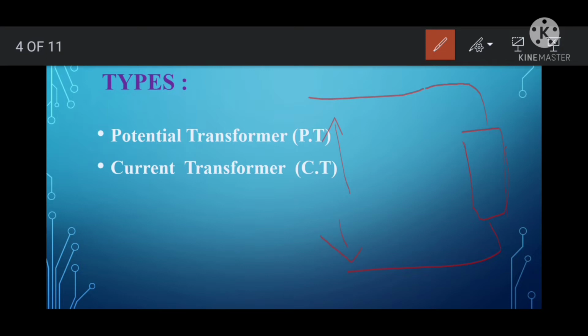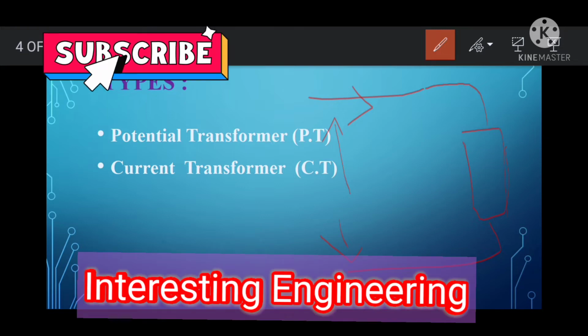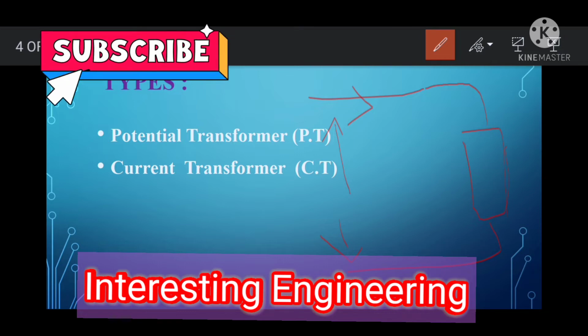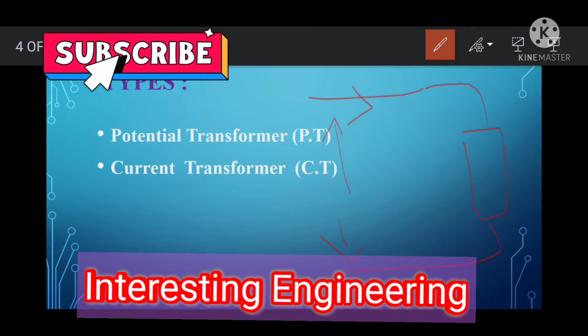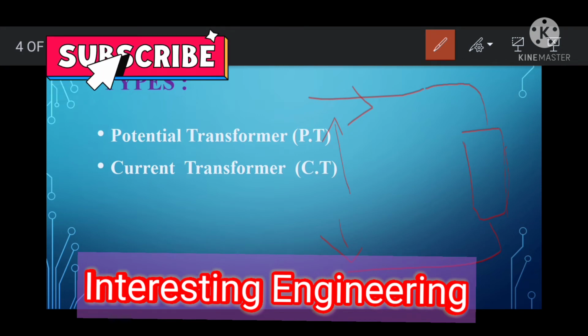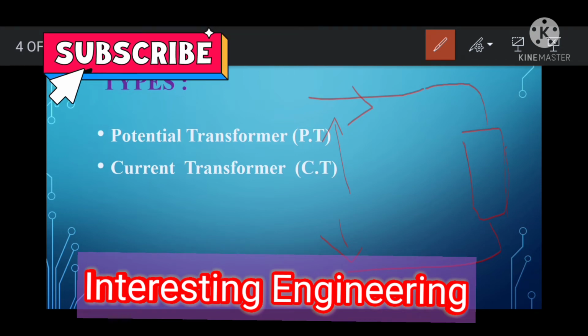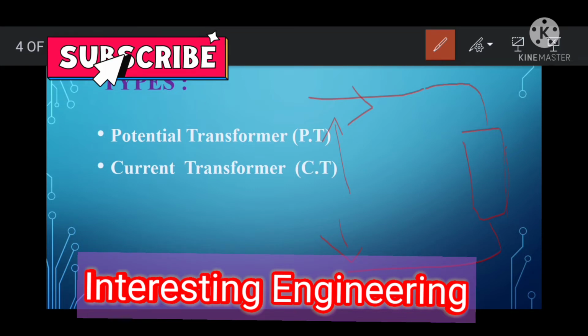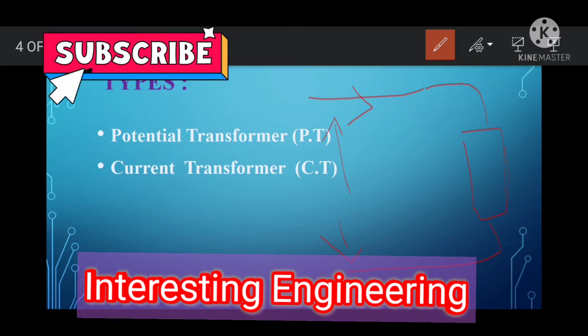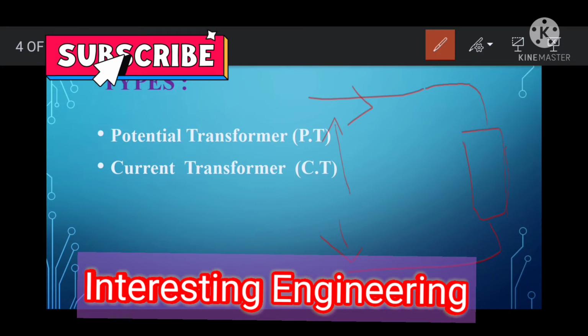If the voltages in this power line are about a few kilovolts, then apart from the voltmeter, we have to introduce an instrument transformer so that the higher voltages are stepped down by means of these transformers. These instrument transformers help in stepping down the higher values of voltages into the minimum operating range.